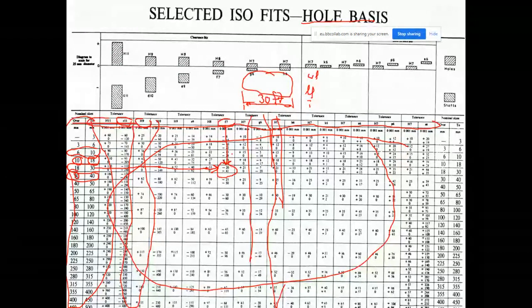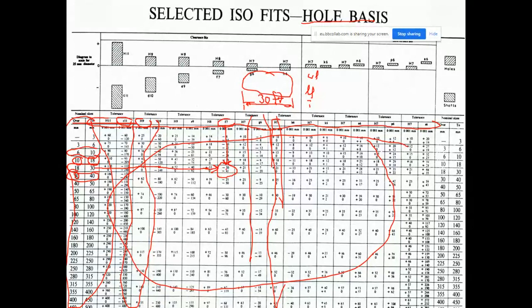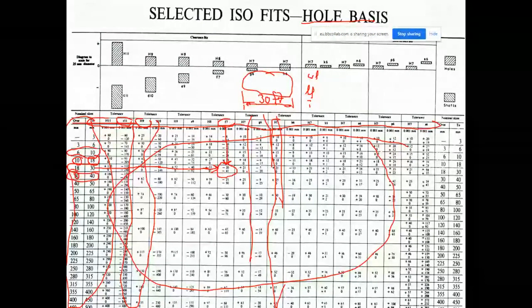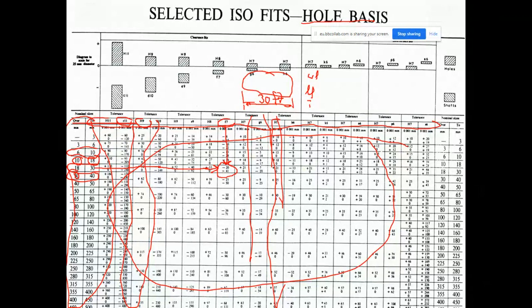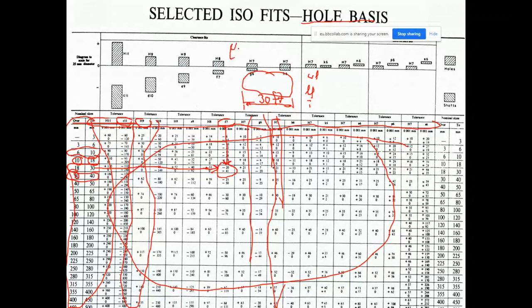Then to this meeting box. Following the IT grade column and the range row, we found this pigeon box. And in the pigeon box, what do we have? Deviation values, both of them negative for this IT grade. But here there is an extremely important detail to pay attention to. In the design of this table, all the deviation values are in micrometers.